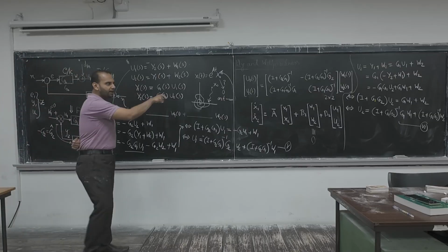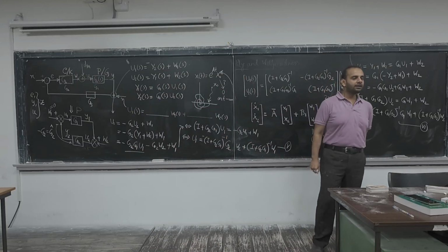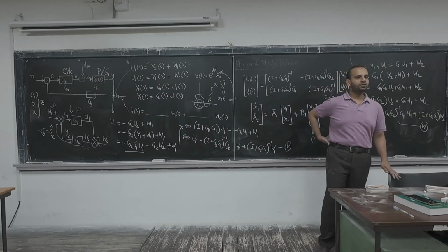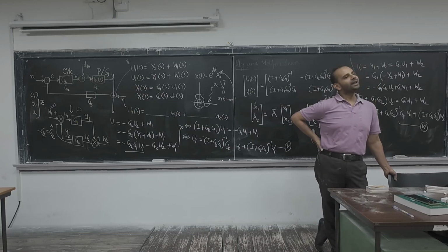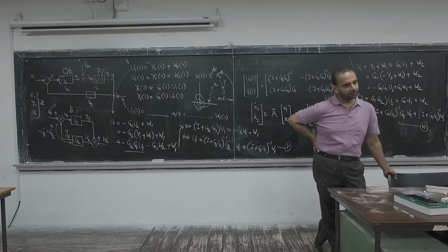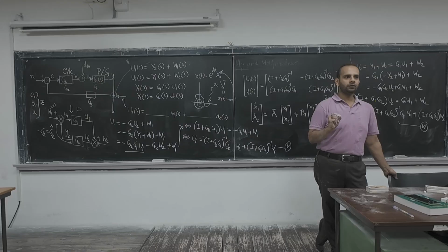The way I explained the H infinity norm by the Bode plot, in the SISO case, (I plus G1 G2) inverse is simply 1 by (1 plus G1 G2), another transfer function. If it belongs to RH infinity, its H infinity norm would be finite, meaning for all frequencies it gives finite values. So if it is so, then we are done.